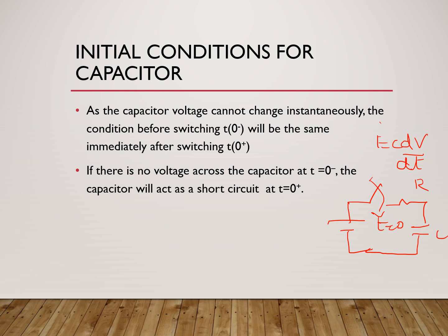So before that, if the capacitance had charged to some particular voltage, it will be the same when you close the switch also, because instantaneous change in voltage is not possible. Or in other words, we can say that V0 minus is equal to V0 plus.